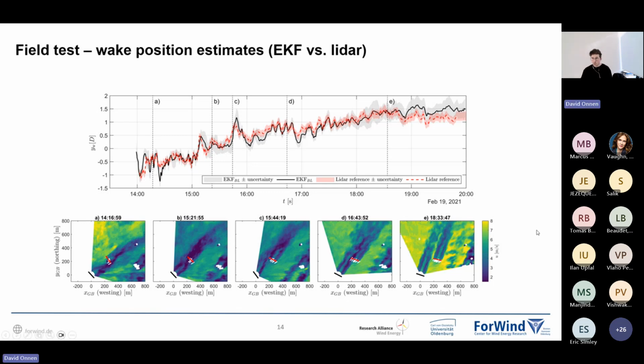And what we see is that the uncertainty bands rise then for the Kalman filter. Here the uncertainty is quite straightforward because we have our state covariance. In the Kalman filter, each state is connected with a covariance, and the square root of that covariance is basically our uncertainty. It only works when the noise tuning is done correctly, but then we have direct information on how certain we are.